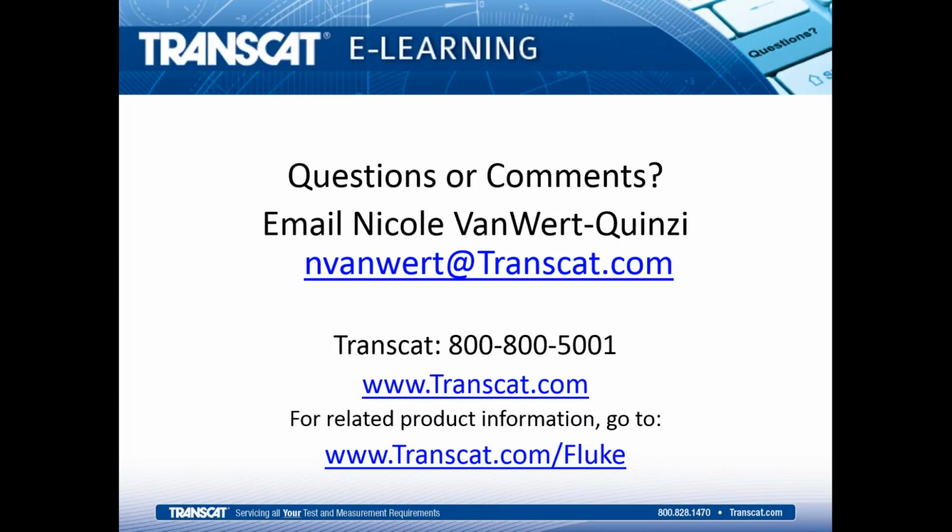So all you have to do is plug the probe into the 9142 or 3 or 9144, and the display will immediately read the calibrated value for that reference thermometer. It's kind of nice. You don't have to insert any calibration coefficients yourself.